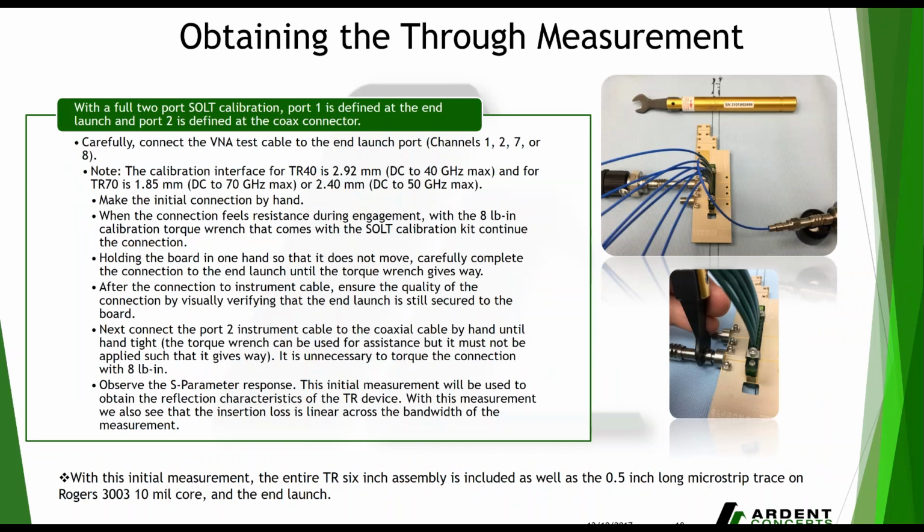So obtaining the through measurement, this here is the procedure for hooking your VNA and test measurement equipment up to our evaluation kit and TR. Carefully connect the VNA test cables to the end launch port, channels 1, 2, 7, or 8.